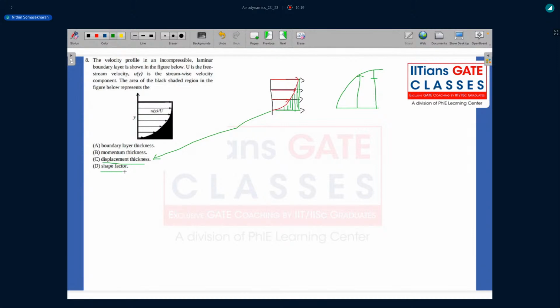how much refinement in the boundary layer we get, because momentum thickness is usually lower than displacement thickness. So by adding more complexity to the boundary layer definition, we are trying to refine how small the boundary layer should be, and basically trying to define it. So that is an entirely different concept altogether. So this definitely won't represent it. So the right option here is option C, displacement thickness.